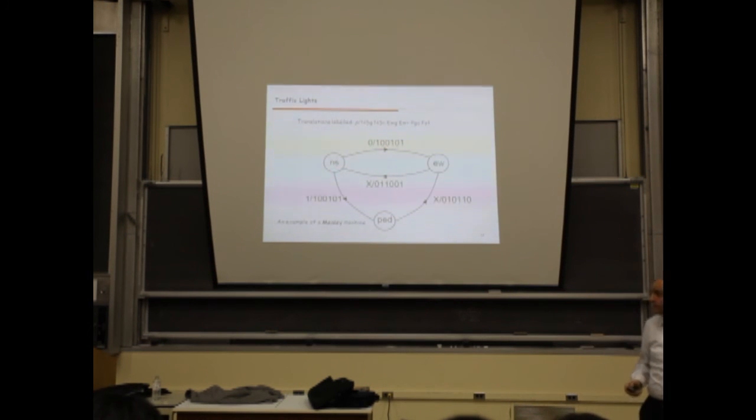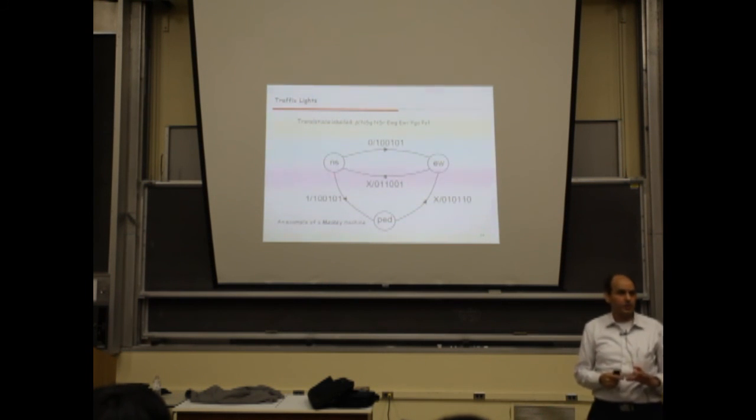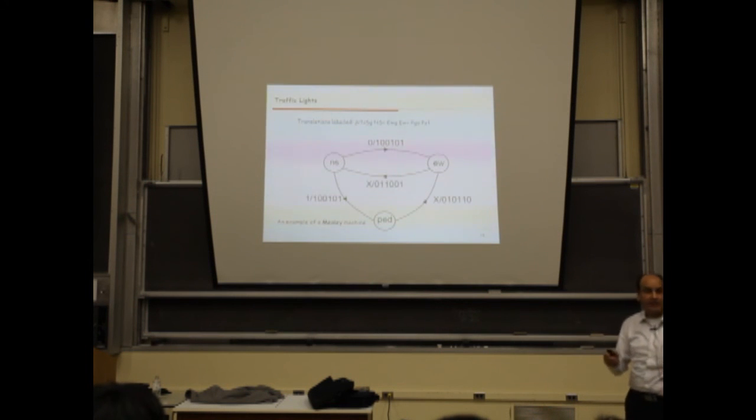So what we are saying here, if nothing is pressed, P is 0, is not pressed, which means there is no person wanting to cross the street, it doesn't matter. You just go from north-south, switch to east-west, okay? Which means you have this one to be green, this one to be red, and this one to be red, which is the person is not allowed to cross.